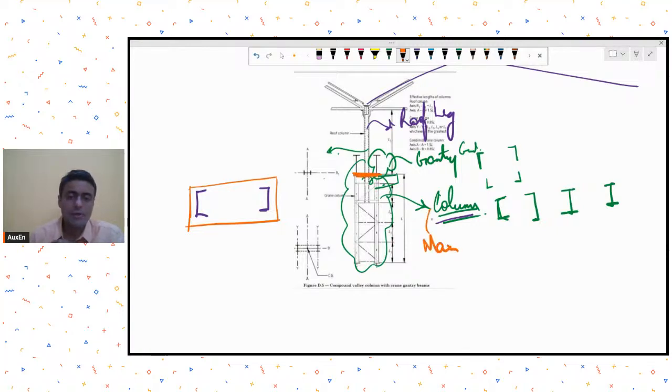On the top of this main column, you will have one plate. This plate will then be connected to another plate which will be joined to the bottom of this roof leg. So let's have this blue plate. This blue plate is joined, let's say, by welding to this roof leg, and then this orange plate is provided on the top of this main column, and then I can have a bolting arrangement made over here. This is one of the options. Of course, there will be stiffeners, etc., to stabilize this connection.